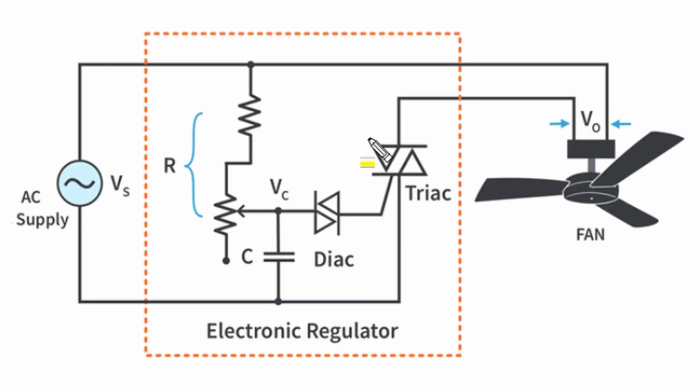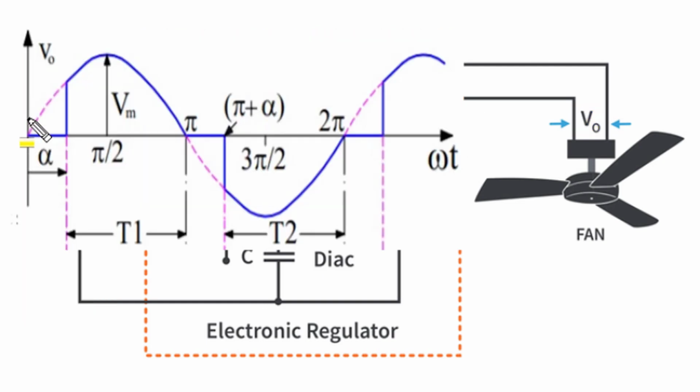A popular and convenient method of speed control by stator voltage control is used in domestic ceiling fans, where we change the applied voltage to the stator of the ceiling fan by using a diac and triac pair. The fixed voltage AC supply is controlled by the diac and triac pair, and the diac controls the triggering angle of the triac. When we control the delay angle of conduction of the triac, and the triac is triggered with alpha delay angle in both positive and negative half cycles, the conduction period gets reduced and the effective RMS voltage applied to the stator gets reduced.